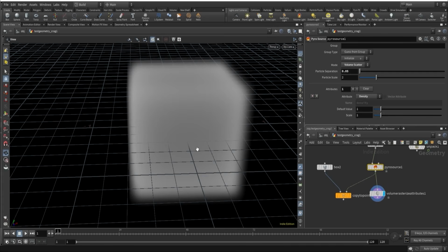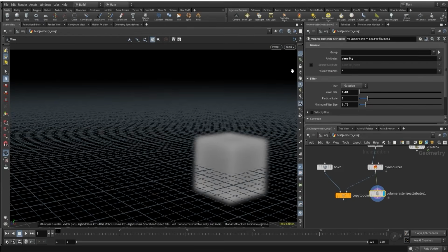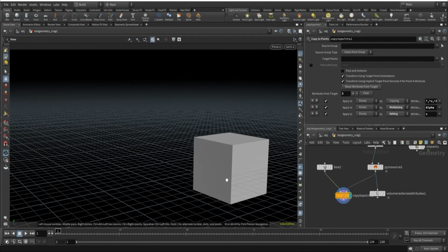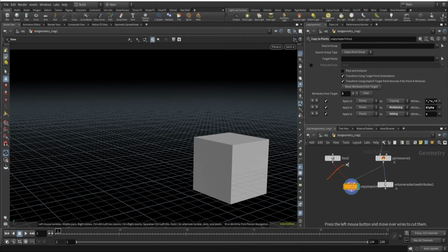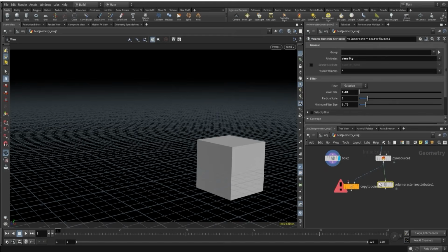But the main question over here is, how do I figure out which voxel size I should choose for this one, right? If I view from camera, I can see it's really far in the distance. Is this voxel size enough for this one? To figure that out, here we can see that this is basically a voxel size as well. Now if I visualize this, I can see this is the voxel size if we keep this at 1 over here.